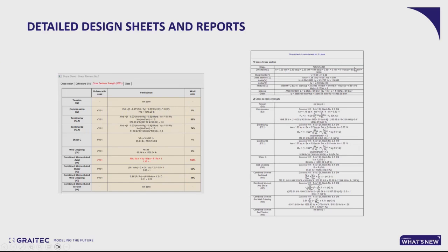First of all, you will have the full properties of that section and material that Advanced Design is using. And here we will have even more formulas. So basically, these formulas are directly coming from AISI code, and you see the chapters and clauses that Advanced Design is using to calculate basically that specific work load ratio. And finally, all of the parameters can be checked from here just to make sure that your design is passing, or even how Advanced Design is calculating those design load ratios if you want to go more into detail.